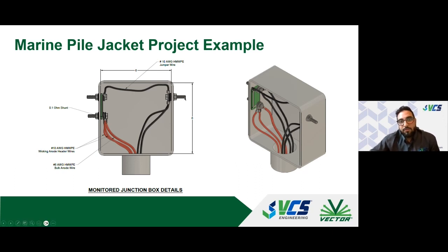And this connection over here, that's a structure connection where we can use it to measure the corrosion potential of the jacket and see what kind of corrosion potentials we're dealing with before and after the commissioning of the system to ensure that cathodic protection criteria is successfully met.